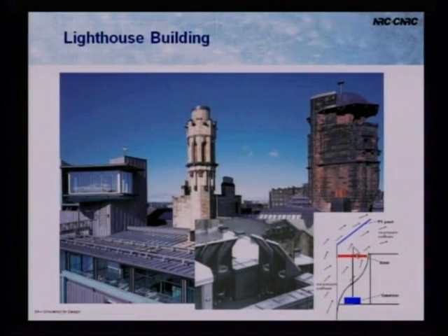What was DWT? Ducted wind turbine, and that's this fellow here. So this was the wind turbine that's suitable for an urban environment. Where I'm tracing with the mouse just now would be the typical building parapet here. As the wind is blowing against this face here, you have an area of high pressure, and then as the wind goes over here, you will always have an area of low pressure here. It's a common failure point in, say, hurricanes and things like that in Florida, on the corners of buildings and at the parapet, because the forces are so strong.